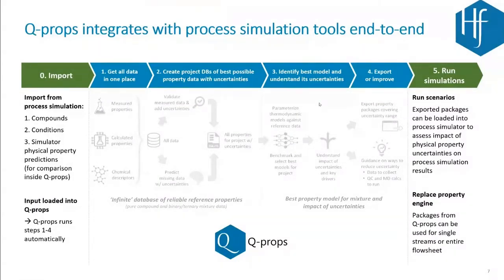Then we can calculate properties and parameterize different thermodynamic models, benchmark them against each other, and finally export this into a single file that we can import through CAPE-OPEN in a process simulation.